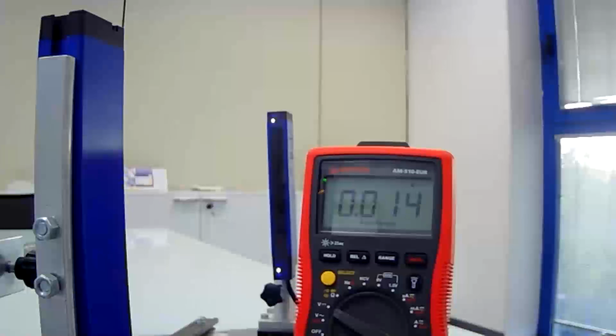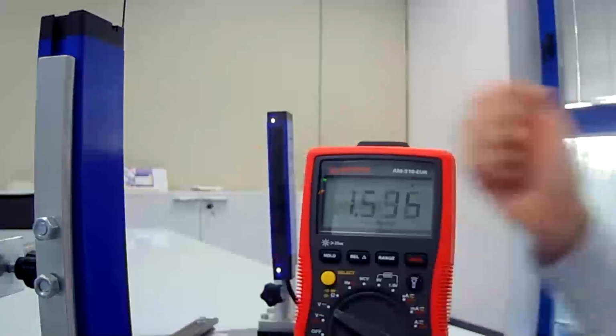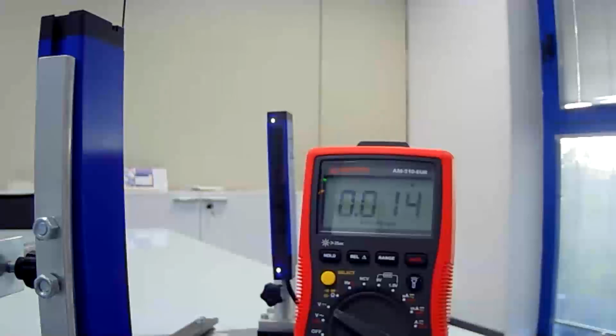Also, the adjusting procedure is the same as the 6.0. You just have to connect the teaching wire to positive or negative for the gross or the fine teaching, and restart the model. After a while, we see that the teaching will be completed and the sensor is working in the correct way. The time is slightly longer than the previous model because we have a lot of things to do inside the sensor. So also in this case, we have adjusted the sensitivity of the sensor.